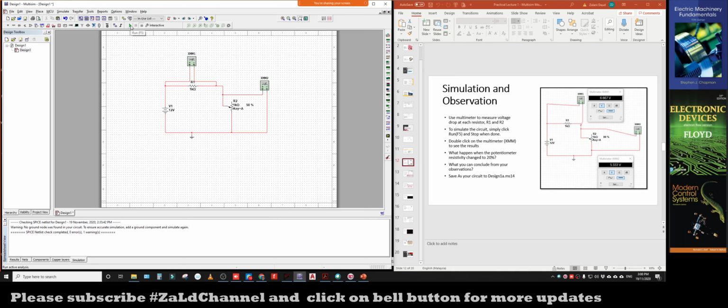So just click on run or F5, then simulate. When you click the simulate, it will continuously do the simulation. It won't stop until you stop it. Once you click on simulation, make sure you pause or stop it. Then basically we have already got the output from this multimeter. If you like to see the output, just double click on the output on the multimeter. Then you will see